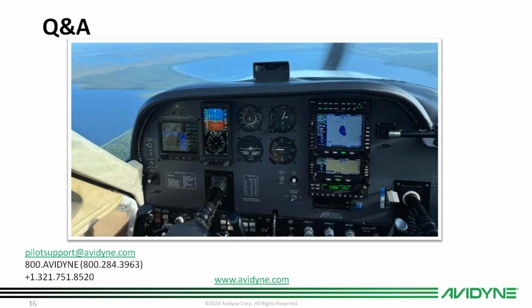Those are all done through a subscription and through Jeppesen. So for the IFDs themselves, you download the data through your computer on the Jeppesen JDM, Jeppesen Distribution Manager app, onto your USB stick, take that to your aircraft, and you upload the databases onto the IFD through USB.